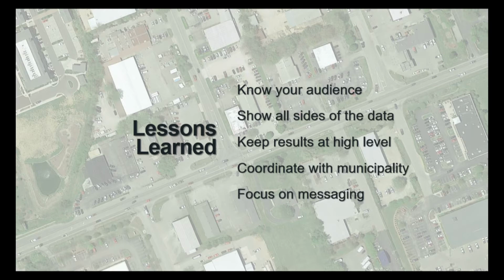You definitely want to think about how the data you present is going to be received. There were some times where we came in with, all right, we're going to show them all of this safety data, and that's going to sway them. They'll see how medians reduce crashes and roundabouts reduce crashes and adding right-in, right-outs reduce crashes. And we came in fairly fast with some of that stuff to try to win them over. And to some extent, that kind of backfired on us.